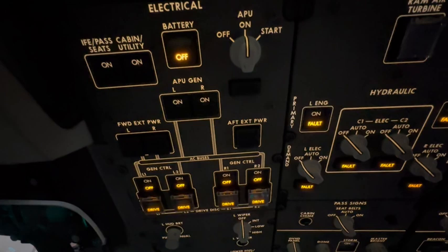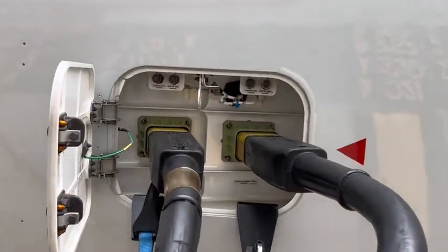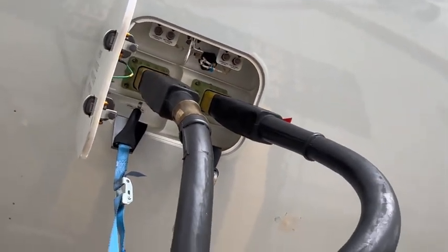This is ground power. Now, you can get the airplane up and running with 1 external power port, but you're going to get the bare minimum. Everything else will be load shedded. It's always recommended to have 2 power ports, which are on the front of the aircraft, left-hand side. But you ask yourself, why do you need that 3rd power port, which is behind the left wing?